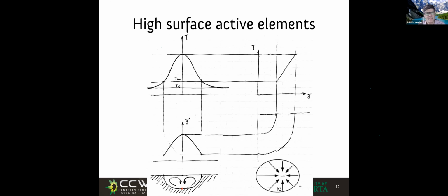Just think how amazing this is, because the heat source is the same. The metal looks the same. They thought, and the funny thing is that these differences in little amounts of aluminum or little amounts of sulfur tend to be within the range acceptable for material specification. So the small variations in oxygen or in sulfur are within the same spec.